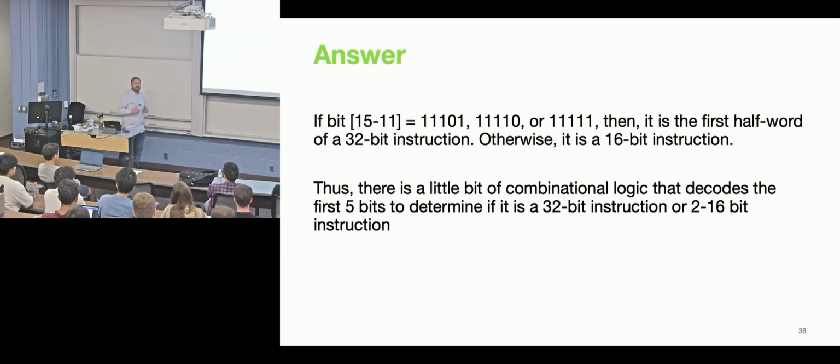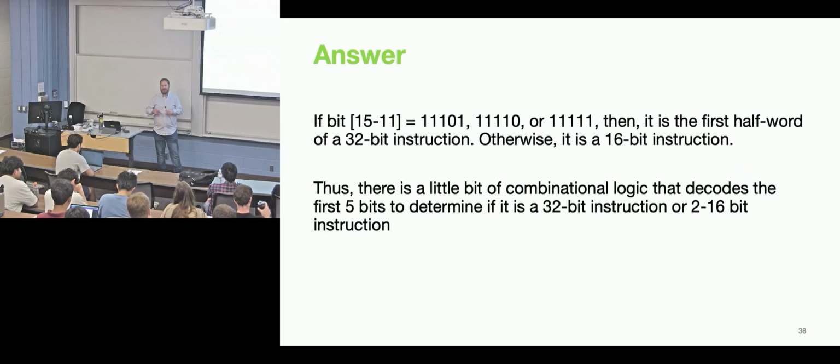They also typically do not allow off-index addressing, so you get a compiler error. For instance, you can't take a 32-bit word if you're not falling on a multiple of 4. Memory is incrementing by 4, and so you don't want to take a 32-bit word out of an increment-by-2 address. They'll give you a compiler error for that.